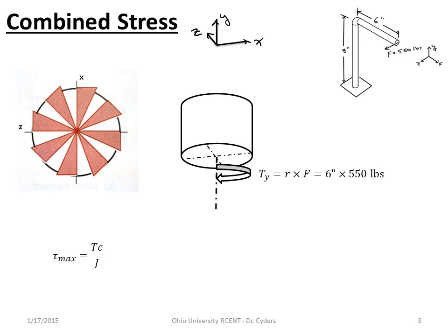And by the way, for non-circular members, this is totally different. In fact, it's non-uniform. In non-uniform cross sections, sometimes the distribution due to a torsion is actually very difficult to describe. Some of them are analytically solved problems that you can just plug and chug into a formula. Others are approximations that we need to solve with finite element code. So in this case, a round shaft makes this easy.